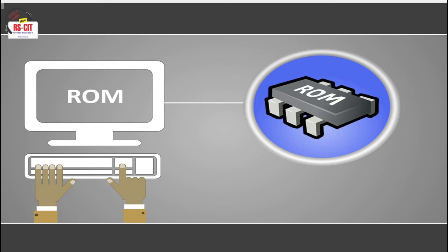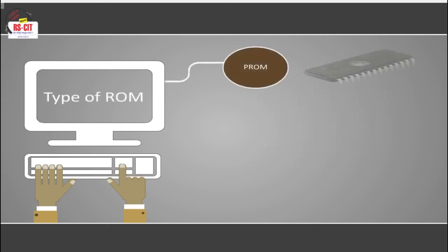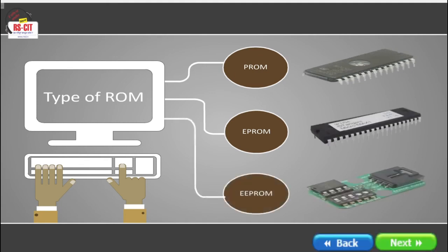ROM, read-only memory, a memory chip that permanently stores instructions and data. Its content is created in the last masking stage of the chip manufacturing process, and it cannot be changed. Standalone ROM chips and ROM banks in microcontroller chips are used to hold control routines for myriad applications. ROMs were also widely used to hold the BIOS in early PCs as well as plug-in cartridges for video games. Types of ROM are PROM, EPROM, and EEPROM.